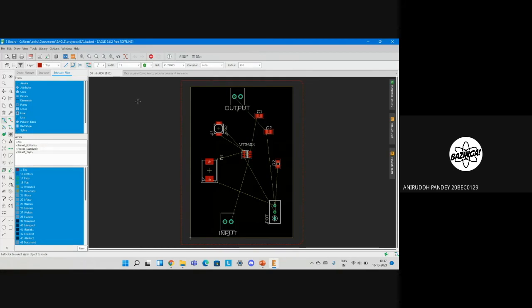So obviously you need a bigger wire for that. For small connections like over here, joining the inductor and the diode, you don't need much width. So at least 12 mil should do. And if you're going to drill a hole, I'll keep it around 20 mil, and the diameter is going to be auto, depending on the width.